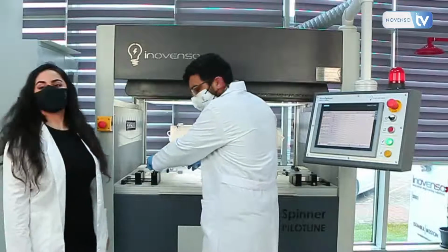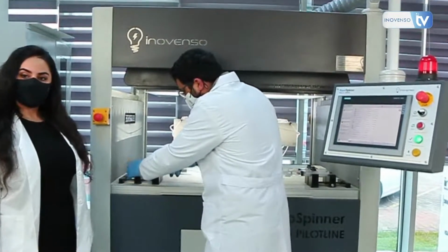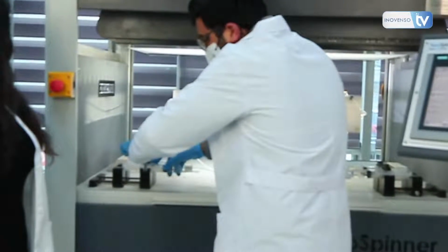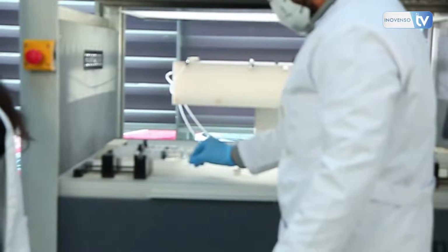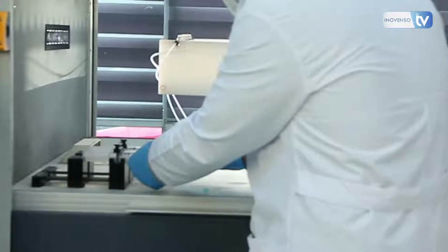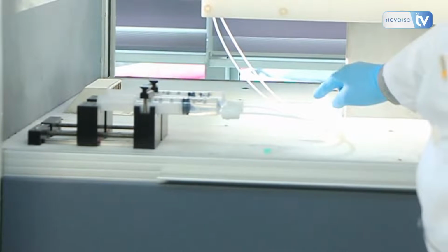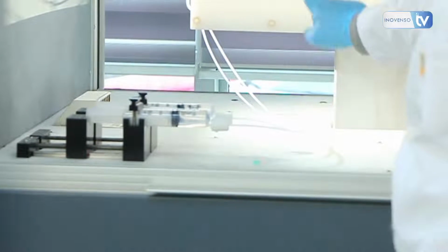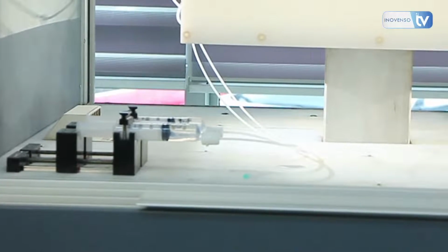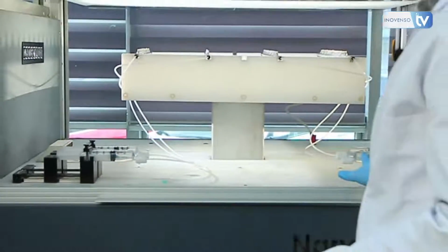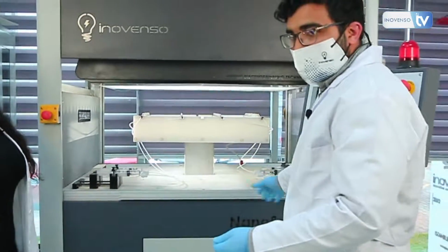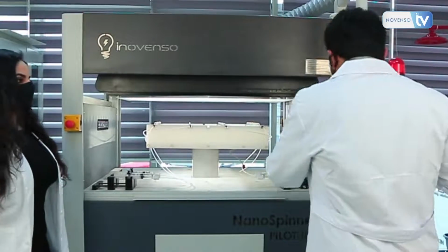So you lift it from here, and you place it in, and you just clip it, you just latch onto it, and this needs to be connected to the polyethylene tubing, which provides a channel for the solution to go all the way to the metal rod nozzles. It's being purged and pushed all the way to the metal rods, where the metal rods are connecting to the high voltage supply. So these are 4 overall syringe pumps, and we're incorporating 4 different syringes with solution. This is a PVDF solution.